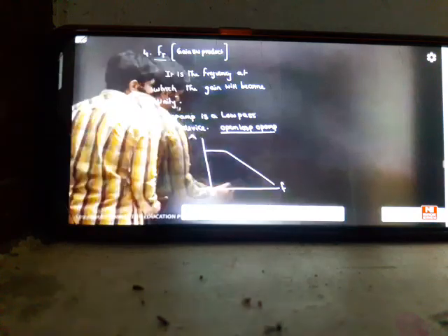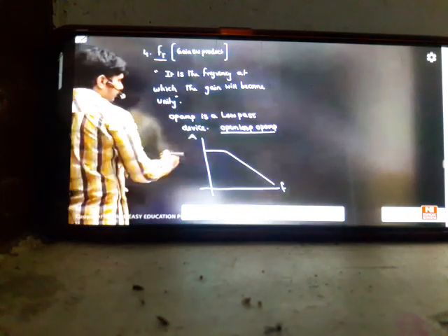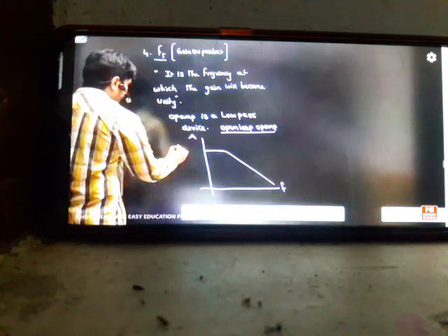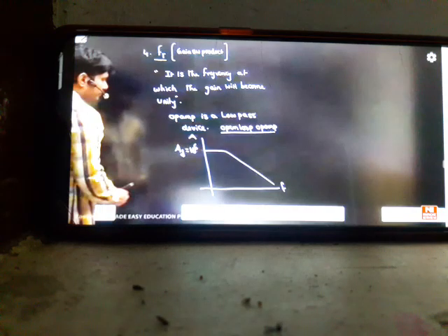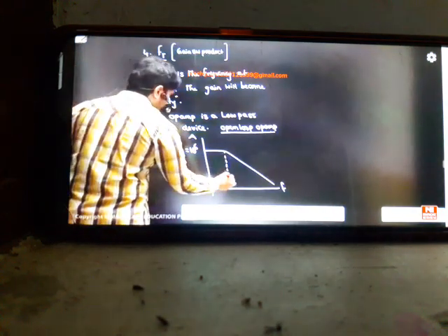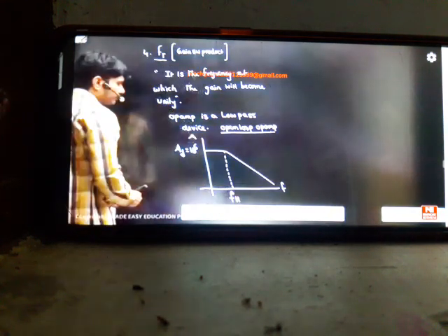He is showing a response like this, saying that it's a low-pass device. At low frequencies the gain is constant, and at high frequencies it is attenuating. Here there is AD. Suppose the designer has given 10^6 as the open loop gain. Then definitely it will have some bandwidth. We'll name this bandwidth FH, the low-pass bandwidth.